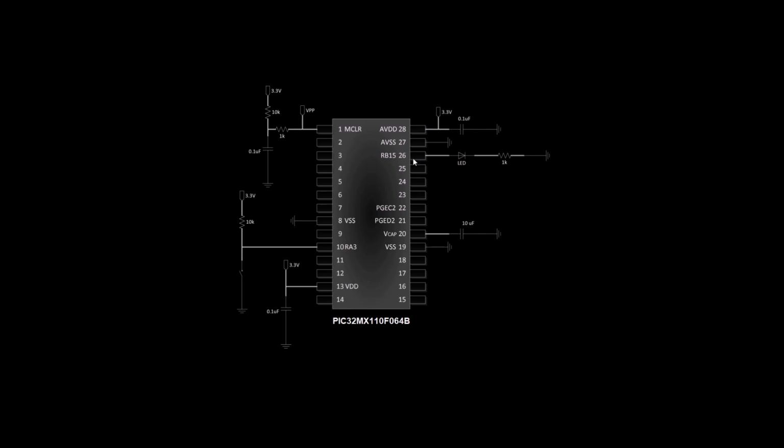It can be seen that an oscillating crystal will not be used, that is, I will use the internal 8 MHz oscillator. The ICSP programming channel, which I will use to program the device, will be number 2. I will also only use capacitors to eliminate noise at the power terminals. The filters recommended by the manufacturer are recommended when building a PCB for a commercial product, and the reset terminal uses the configuration and resistor and capacitor values recommended by Microchip Technology.